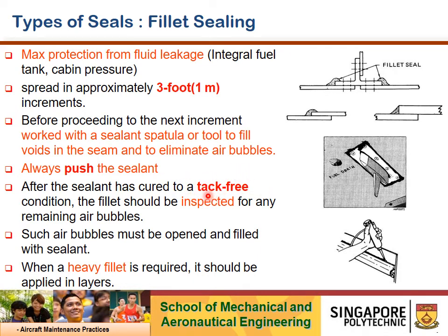But what do you mean by tack-free in this case? It will be when you use a masking tape or a tape to touch on the fillet surface, it shouldn't transfer any sealant onto the tape when you remove. So that's tack-free. Same thing, you use your hand to touch it, the existing sealant should not transfer from the fillet seal to your hand. So that's considered tack-free condition.